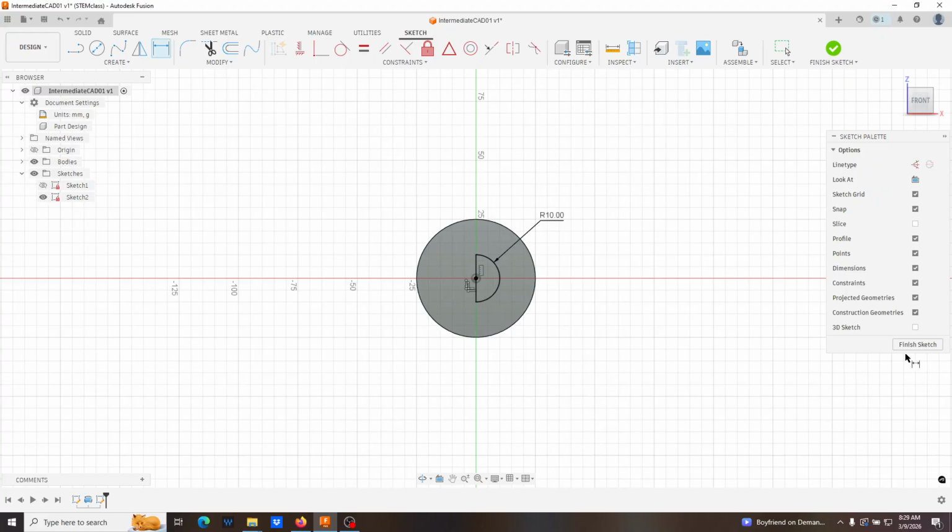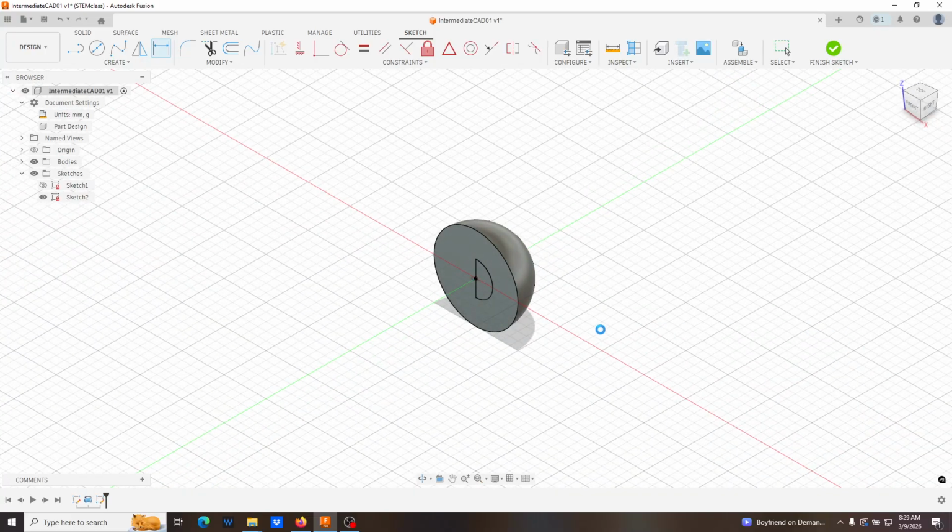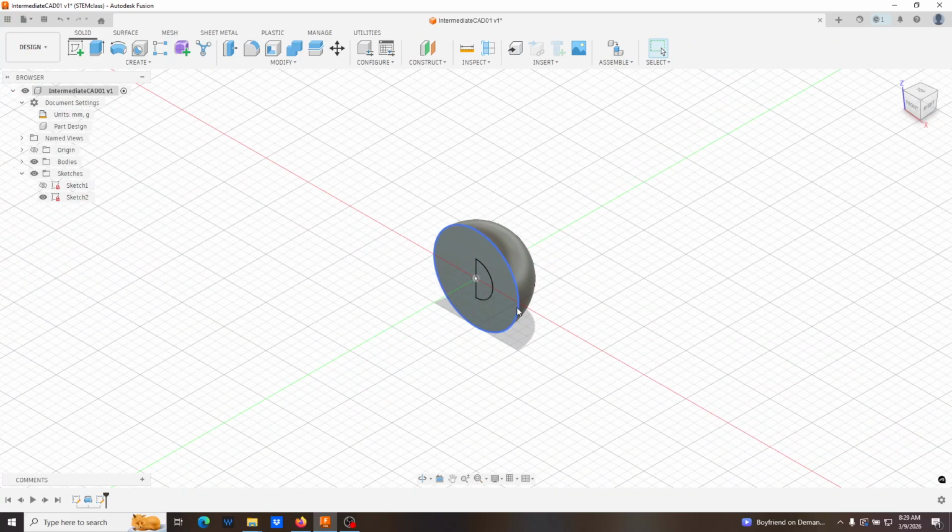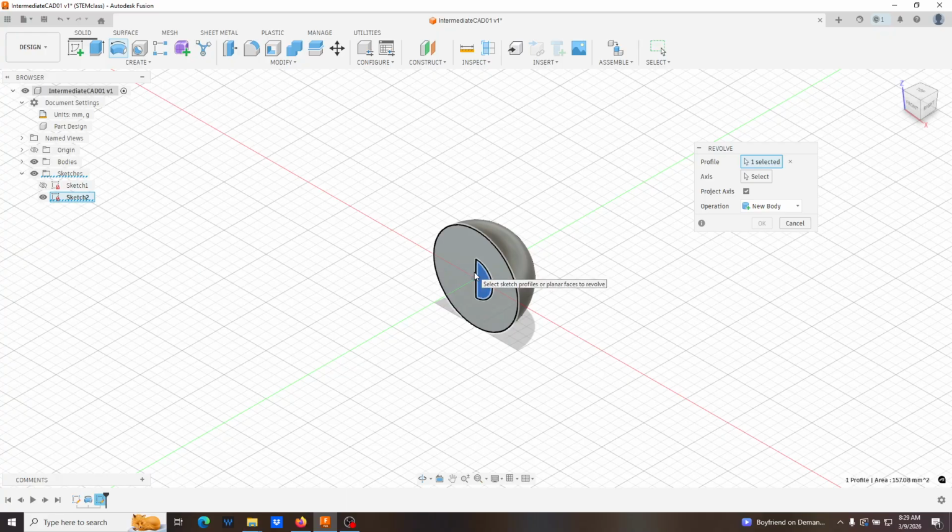Cool. All right. Now, one of the things is that we've seen how we basically create a solid object by moving a profile through space. We can also do that with revolves as well. We can take away material by moving a solid object through space. So I'll go here with revolve. I'll set for this, and then I'll pick my axis just like I did before. You always want to keep good track of what you're selecting. Go ahead and hit the axis here.